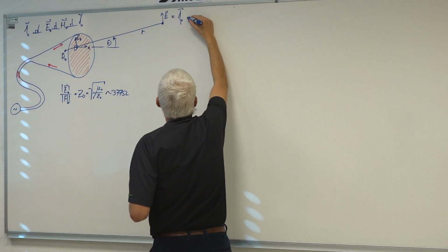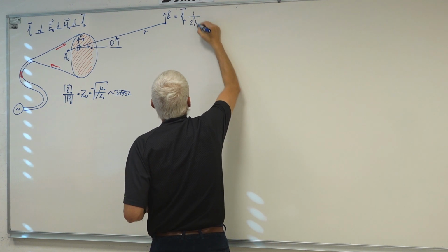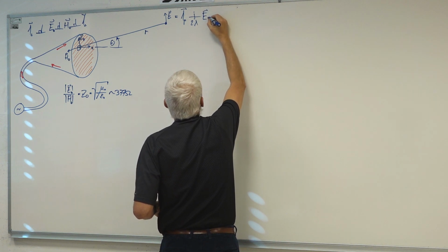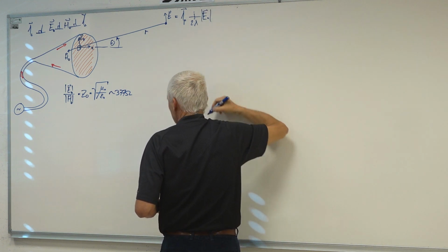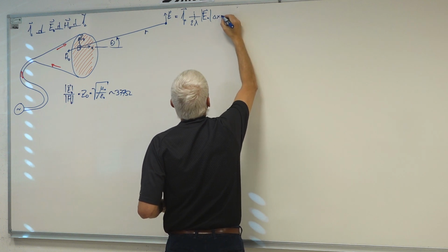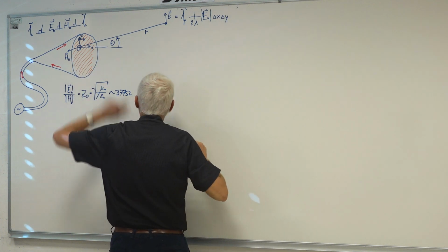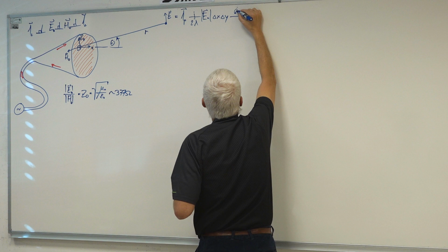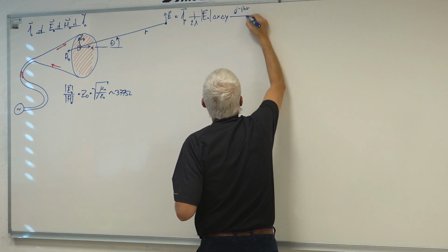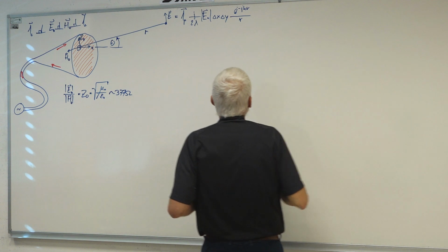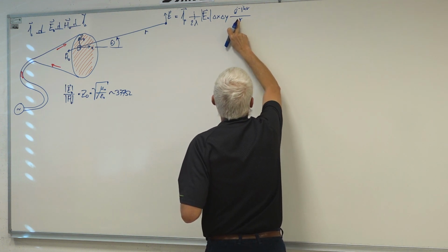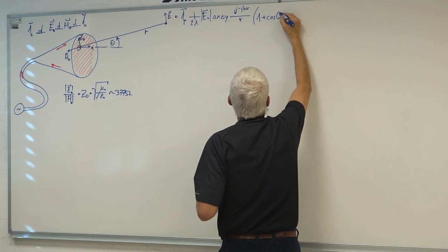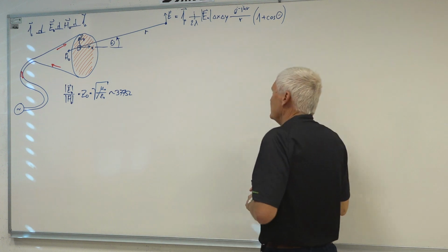Okay, there is a physical constant, j over 2 lambda. There is the field on the aperture, E0, without polarization, I write it this way. Delta x, delta y is the size of our Huygens source. We do have radiation, so we have delay, e to the minus jkr, divided by the distance r. And we have some radiation pattern of the Huygens source. It's not particularly complicated, 1 plus cosine of theta. This is the cardioid radiation pattern.